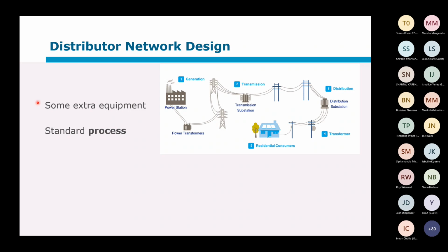On the protection side, something that I can think of quickly is your reclosers. Remember the plant or the generation, no, this is the wrong picture, but the generator has 2 seconds to disconnect if there's an island connection. So if you have a recloser that is going to reclose in less than 2 seconds, that could be a problem. And I also know that Andrew will speak about this afternoon.